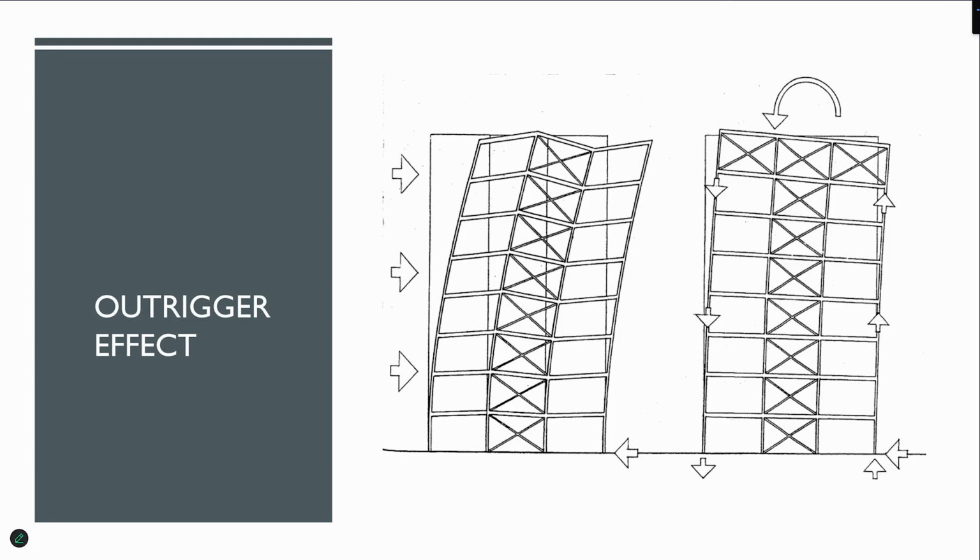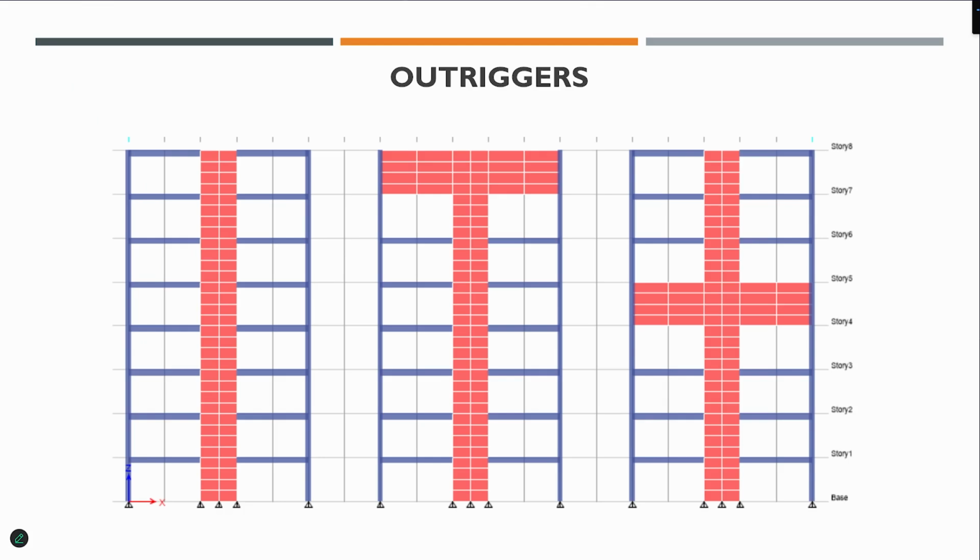So this is the way that we use the core wall, which is already converted into a shear deformation mode, a shear system, and then we add another one on top, and then the columns just become sticks. So the columns become just sticks, beams become irrelevant, and the whole system works as a wall, outrigger, and columns supporting axial forces. Okay. So we can see from here the effect.